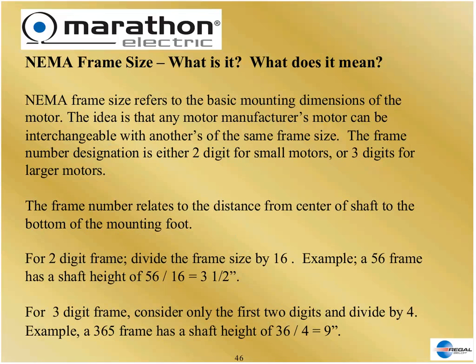They do make sense. The idea of the frame size is for the motor manufacturers to manufacture specific mounting issues with the motor, the shaft diameter, the foot, the holes in the feet, the holes in the C-face, all to the same dimension.